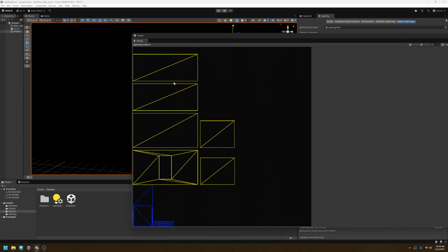So what this is, a light map is a second unwrap on your models. Anything that needs a baked map needs a second unwrap. Back in the day, this used to be the job of the interns. We would toss them the models and say, please make the light map unwraps for these. Thank you. Because it is a little bit tedious. We can't have any overlapping UVs. But the nice thing about that button, generate light map UVs, is that now the program will do it for us. You'll get some purists who say you should still do your own light maps.